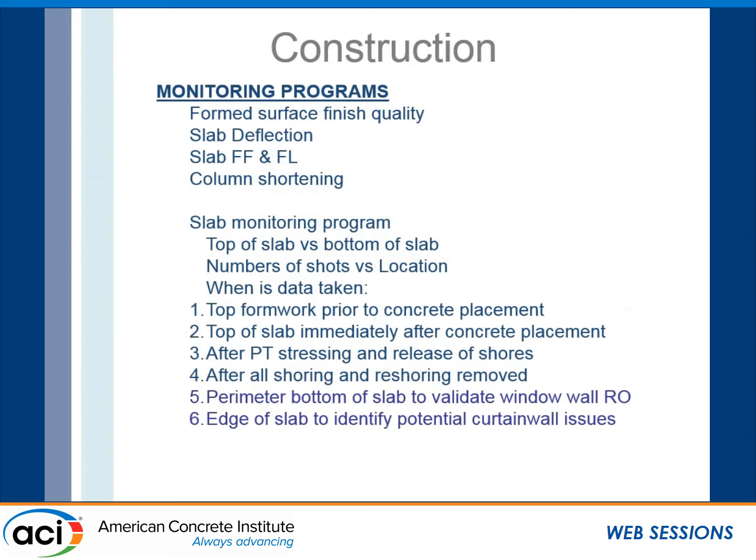And then we have our monitoring program. What we're trying to monitor as we construct is formed surface finish quality, slab deflection, slab FF and FL, but as stated multiple times previously, FL is not really appropriate for supported slabs after the shores are released, and especially not appropriate for cambered slabs. And monitoring column shortening. In our slab monitoring program, we're measuring the top of the slab versus the bottom of the slab, so we're measuring the formwork before we cast, and then measuring the top of the slab after we cast. And then the number of shots and location.